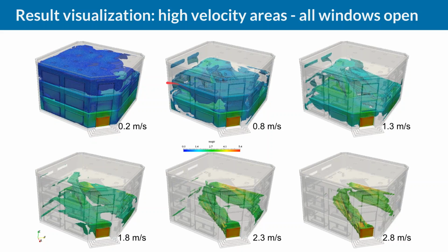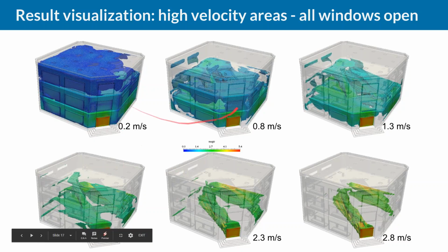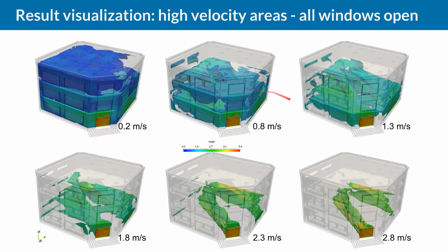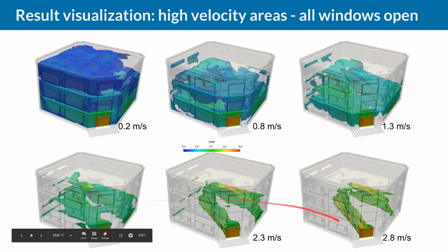And the more I go toward the center of this building, the wind speed is increasing. It's a little bit like those Russian matryoshkas, like an onion. So the very outer layer is fine. The more we go inside, we can see the wind speed is increasing, and actually we have large thresholds, like this whole part here, where we have really high wind speeds.